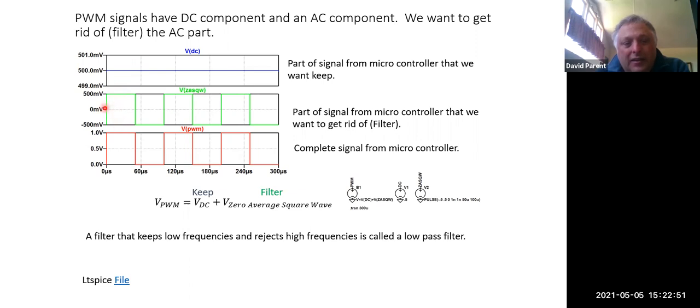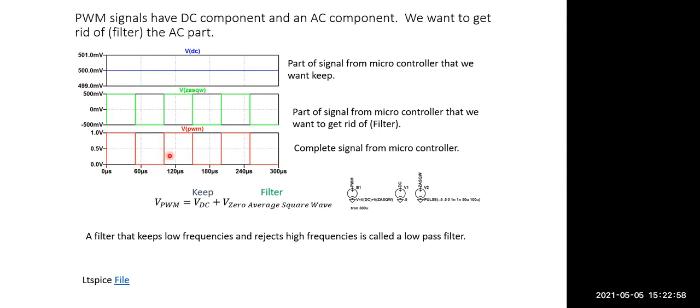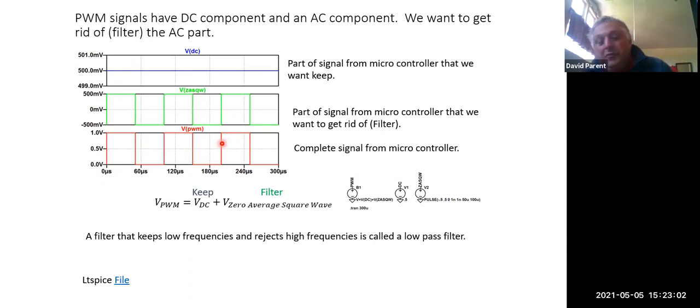Look at the thing in red here. It goes from 0 to 1 and back to 0. So just looking at it, you know that there is a DC component to the Fourier expansion. By now you should be able to think that looks like it's 50% on, and it's probably 90% chance that any square wave I show you will be a 50% duty cycle.